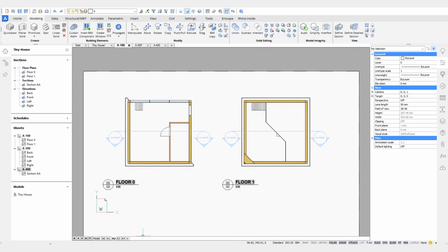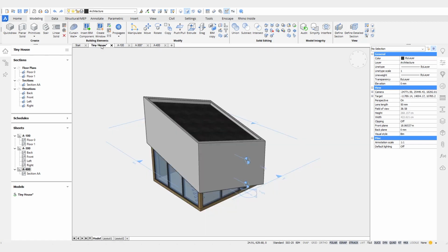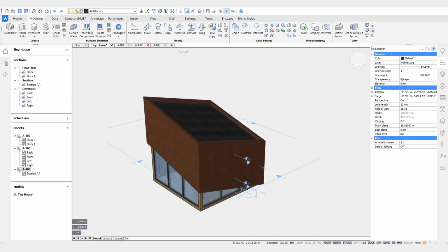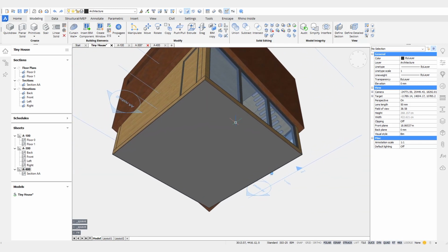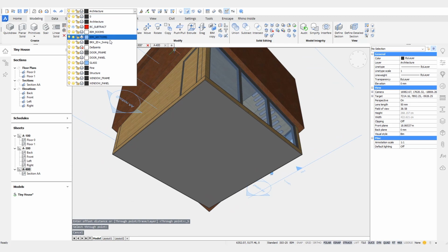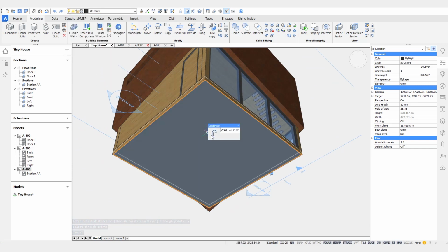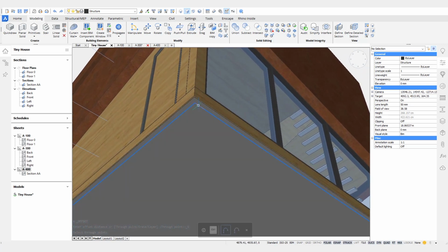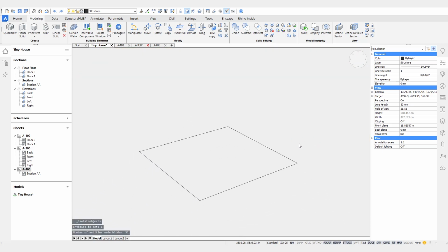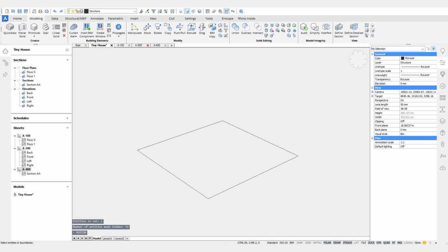So I mentioned before that the building would be supported by a steel structure. So it's just a steel frame. Maybe it's time to take a look at that now, so I can start creating a frame, but I'll start by creating a wireframe model, so just lines that show the shape of my steel frame, and then later I can assign profiles to them. So I'll use this line as a basis, and I want to have a steel frame with at the bottom, basically I want to divide this into 3 by 3 cells.